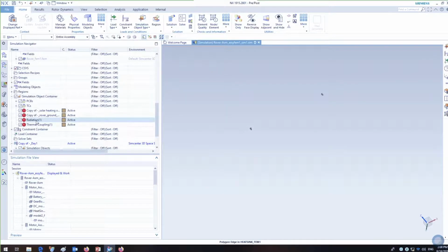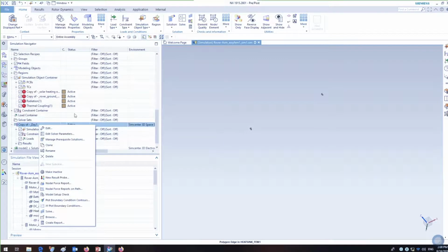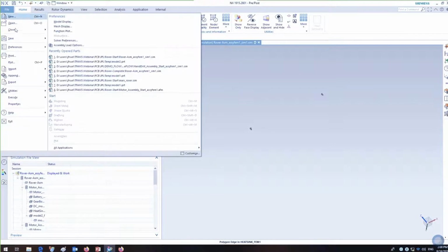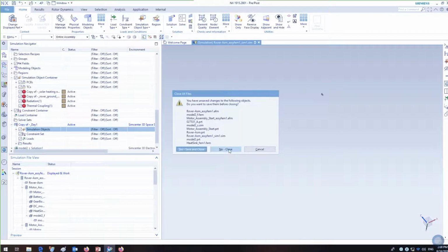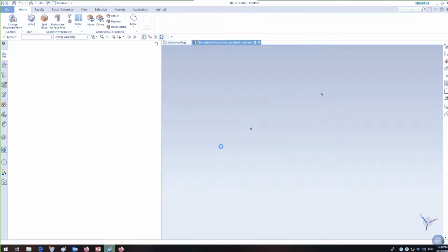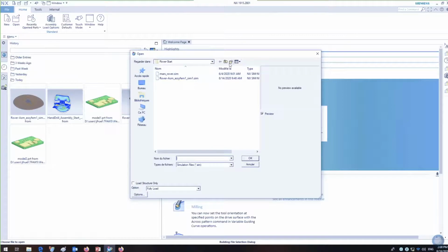Here we go. And this base. Then we'll do a conductance value, and voila, we have our conductance defined between the board's objects, the heatsink. We reused our mesh as well as our boundary conditions. We would then be ready to solve this model. To save some time, I already ran this model, so let me open that up.